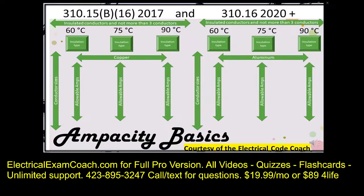If you need to watch this video over and over, you can do it. The first distinction we want to make with this table is that it's actually two tables. On the left-hand side is going to be for copper conductors, and on the right-hand side is going to be for our aluminum and copper-clad conductors. Left-hand side copper, right-hand side aluminum. And if you'll notice, they mirror each other, but in the NEC, it's smushed all into one table.